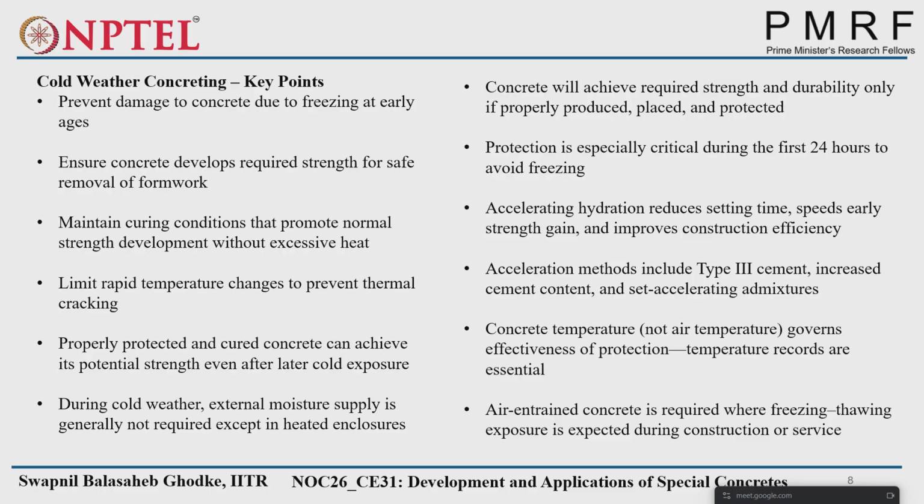If you are producing the concrete at the RMC plant and going on to the site, you should have a correlation between them. So whatever the temperature effects, we have the lab at the RMC plant and the lab on the site. According to that, we have to make certain changes on the site in hot weather as well as cold weather conditions.